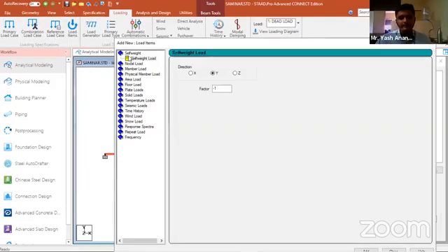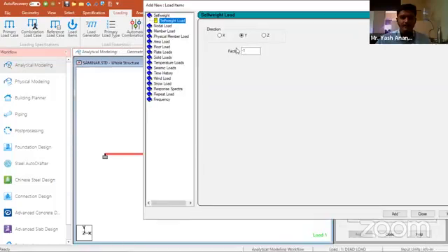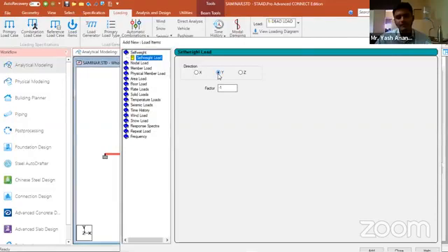See, there is a self weight. Okay, self weight load. In which direction is it acting? In the y direction. Here the y direction is upward, where the self weight is acting negative to gravity. Okay, sorry, positive to gravity. What it means is that our y direction is up, so the gravity force is acting in the minus y direction, so I provided -1 for y.